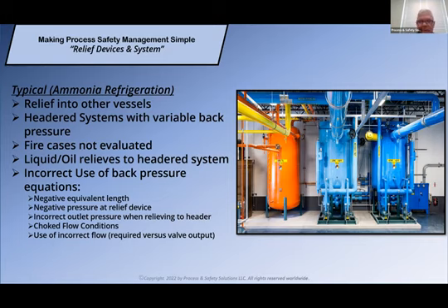Incorrect outlet pressure when relieving to a header. If we're relieving into a header, the outlet pressure most likely is not going to be atmospheric. It has to be something other than that, because there are many diameter changes of that header system before you get to atmosphere. Have to make sure that you're evaluating or using those equations based on choke flow or non-choke flow conditions. Can't use that equation if you have choke flow. So making sure that we're looking at those outcomes again to make sure that we're doing those correctly.